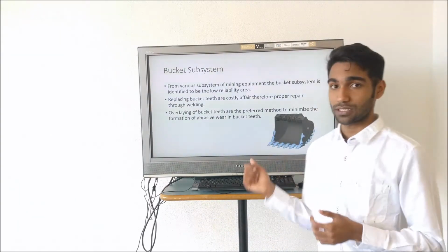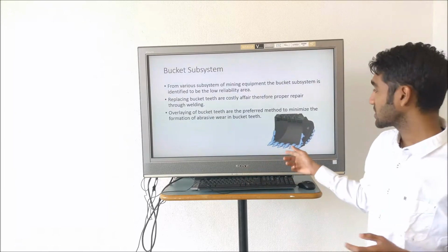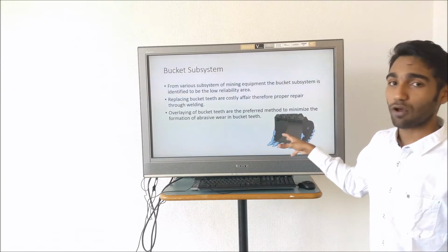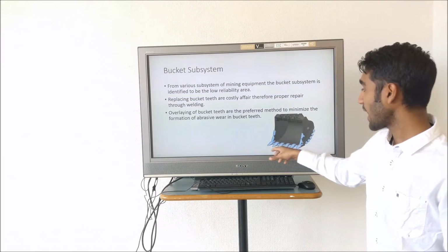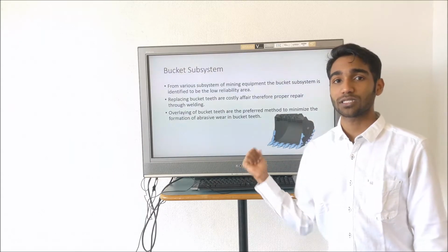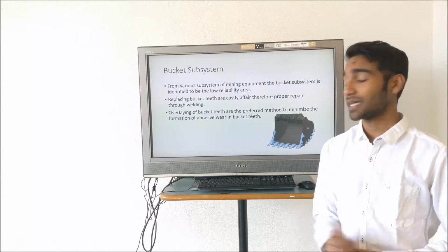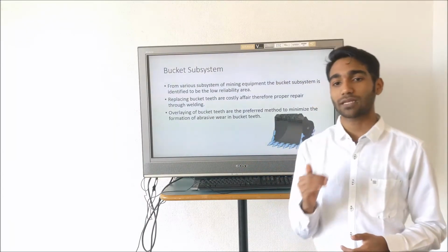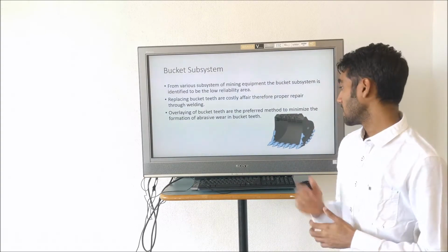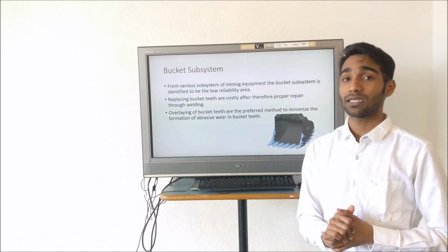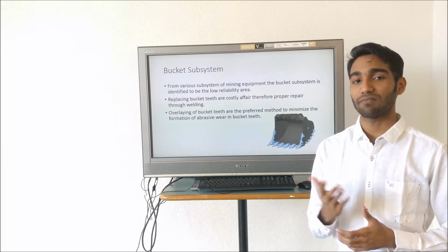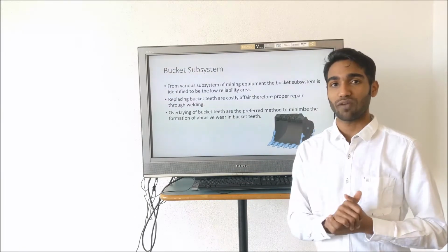Now the bucket subsystem. The figure actually shows the bucket attachment of a mining system, and this highlighted part is known as bucket teeth. These teeth are subjected to high abrasive wear, as these are the parts that come in contact with the abrasive particles being excavated, and necessary design changes have to be made on the bucket teeth so that they can withstand abrasive wear.